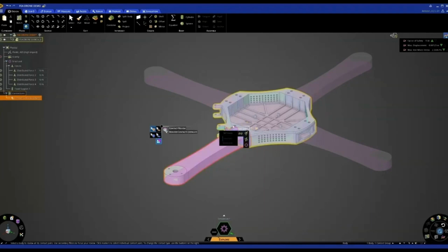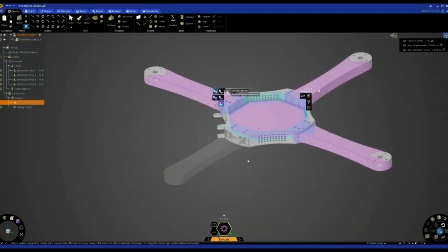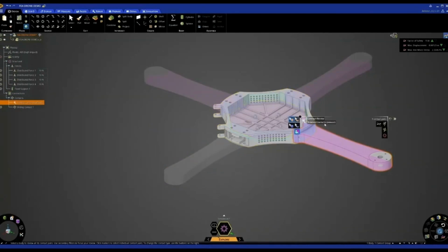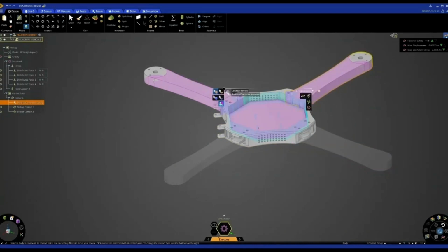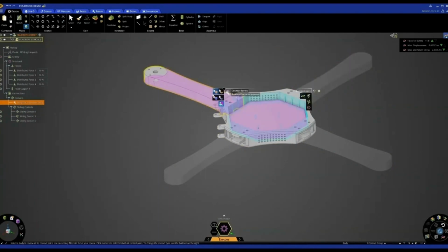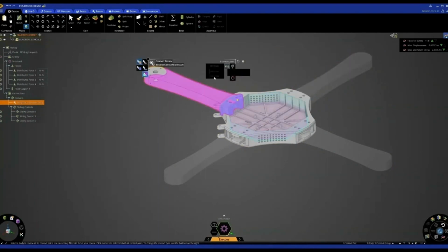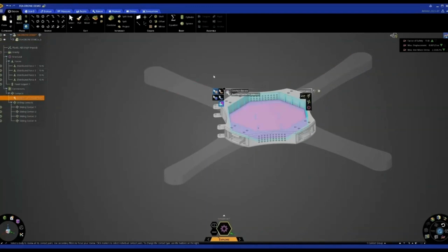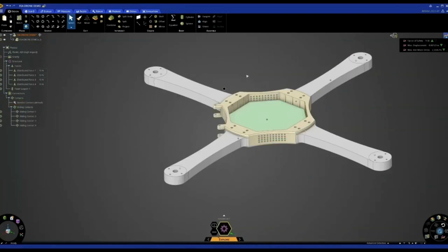Because it looks like obviously we've got some bolt holes that maybe will hold this part together, I'm just going to convert those to sliding. We'll do all the same to these, and we can go through them very quickly and just convert these to sliding. You can also see that we can use idealized or frictional, but I'm going to just use idealized for the time being. So now we can see that the bonded contacts, I'm just left with this sort of plate on here, which I'm okay with.